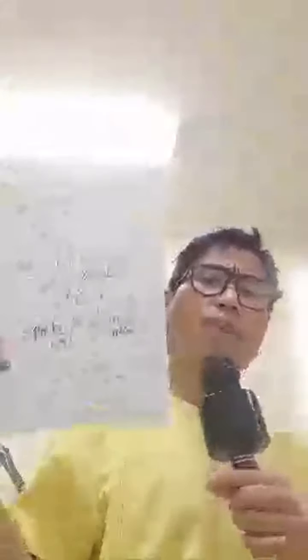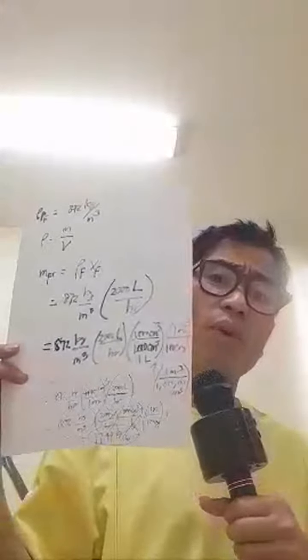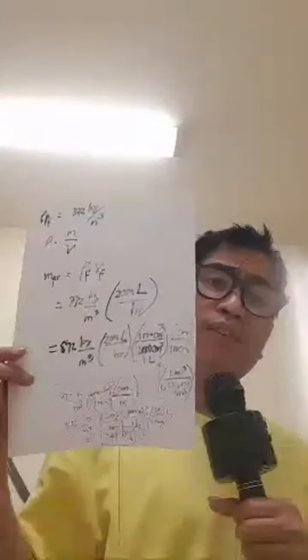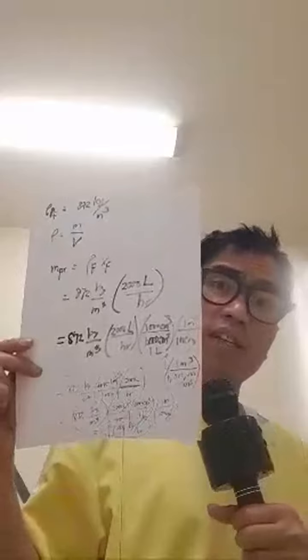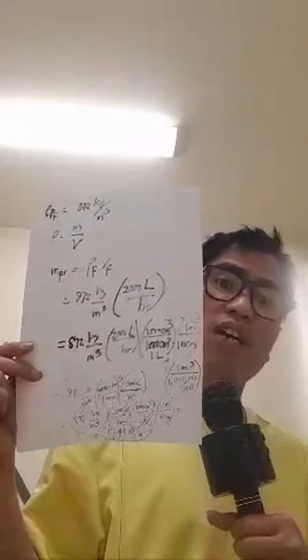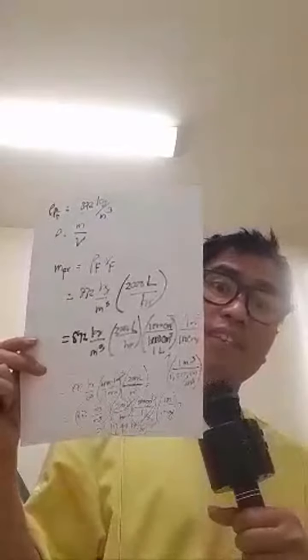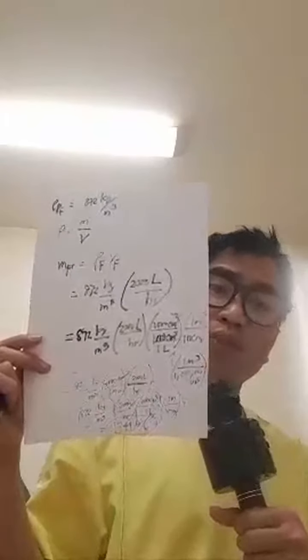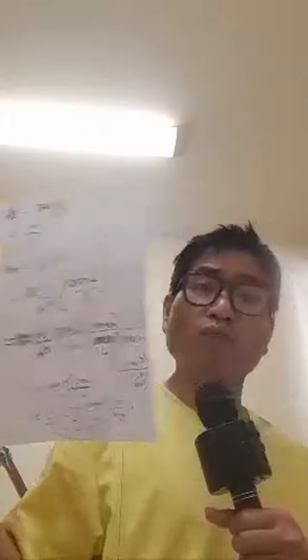So we have 1,744 kilogram per hour. So this is now our mass flow rate of our feed mixture. Our main reason is to convert it to the mass flow rate because the required is asking for the mass flow rate, not the volumetric flow rate. That's the only reason. It's just a conversion, but the same principles hold through. But it's easy to do that first because it will complicate things somewhere along the way. That's why we need to convert first. So 1,744 is our feed.